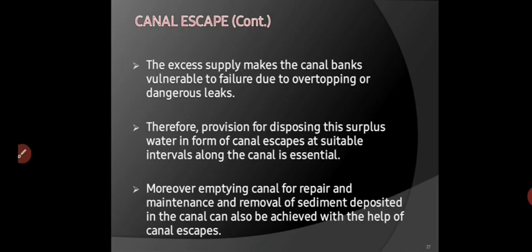Therefore, provision for disposing this surplus water in the form of canal escape at suitable intervals along the canal is essential. Moreover, emptying the canal for repair and maintenance and removal of sediment deposited in the canal can also be achieved with the help of canal escape. So these are the function or purpose of canal escape.